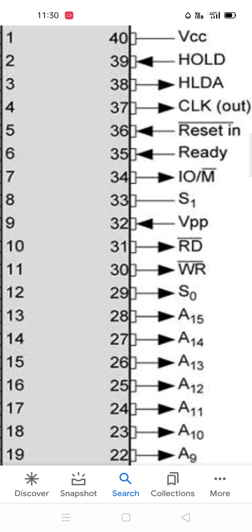Okay, IO/memory is like input output or memory, which kind of operation. The processor can do data transfer in only two modes. One is an input output mode, or it can have a memory mode. Memory mode means DMA and other things can be used, or a register or a latch can be used. That is called a memory mode. IO mode is basically for other kinds of things like an interrupt mode, and if you want to do a serial transfer, you can use IO mode. Okay, S1 and S0 are the status signals.